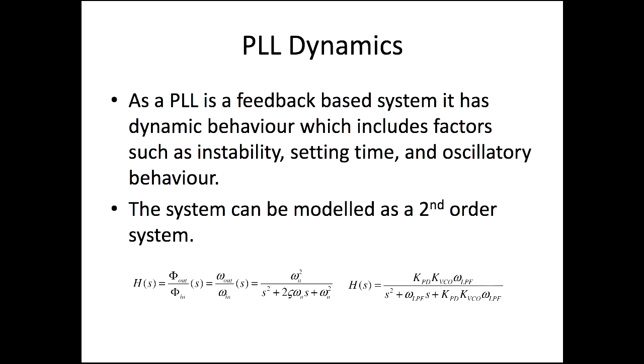If the center frequency equals 1 kilohertz, then maybe 900 hertz you can connect in that range, and it will be okay. The PLL will adjust; 1K may be adjusted to 900. The center frequency could be 1 kilohertz, but if the data frequency you connect to the input is 5 kilohertz, you know what I mean? The PLL in the real world will not do it; this 1 kilohertz will not become 5 kilohertz.